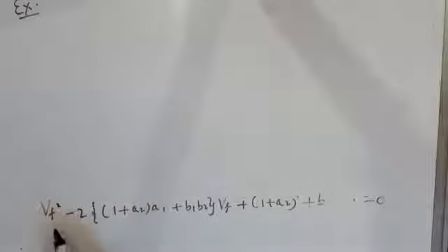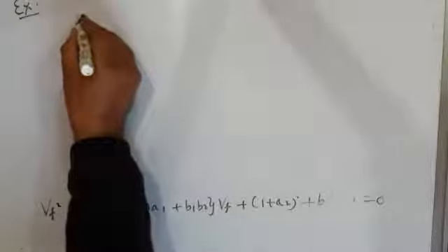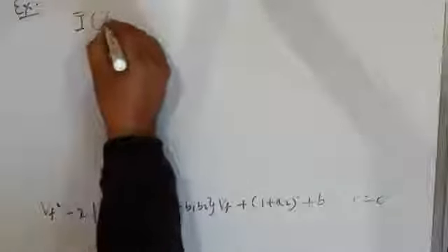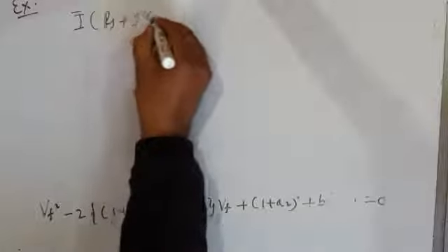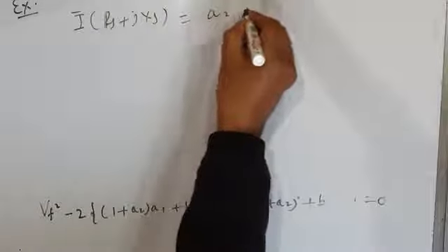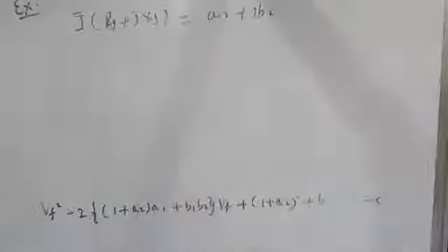A2 and B2 will also be found because when we were computing the DVR injected voltage, the compensation voltage, we assumed that I into (RS plus jXS) is equal to A2 plus jB2. Okay, we assumed this, it is equal to this.